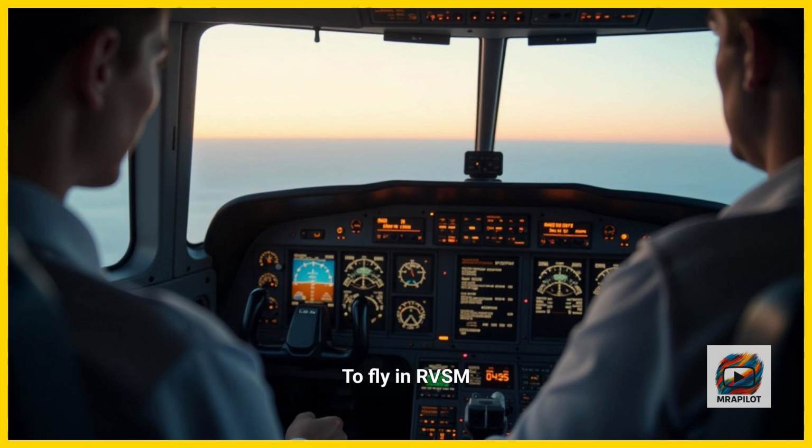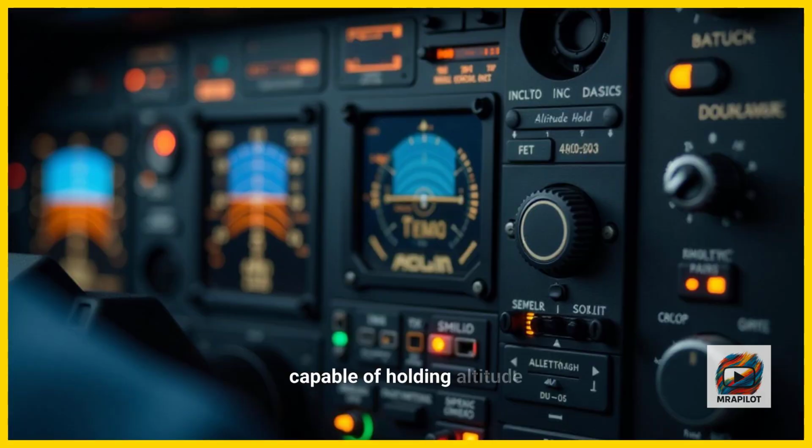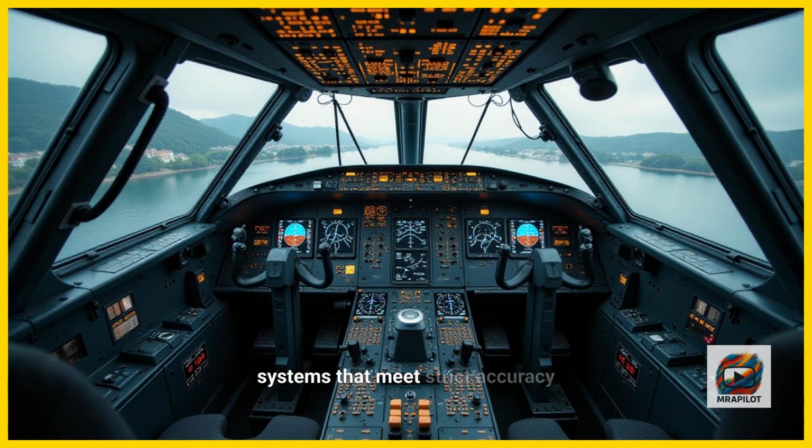To fly in RVSM airspace, your aircraft must be specially certified. It needs dual altimeters, an autopilot capable of holding altitude precisely, a transponder with mode C or S, and systems that meet strict accuracy and redundancy standards.